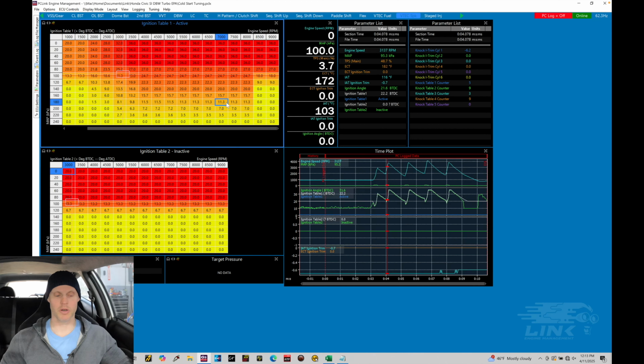So once we started to put in reasonable spark timing values and we were coming back down to about the gate spring, about 130-140 kPa gate spring, we were finding that we were riding right about here. We were commanding right around 20 degrees of timing. On this 12.5 to 13-to-1 compression engine on petrol fuel, that's not bad. We saw that the knock sensor was set up. We weren't getting knock. Everything looked to be in order there, and that's where we backed off, primarily because, number one, I'm playing with a razor edge with knock with this engine being such high compression on 93 octane. But number two, we're going to do a flex fuel tune, so I don't need to push things like crazy on petrol fuel.